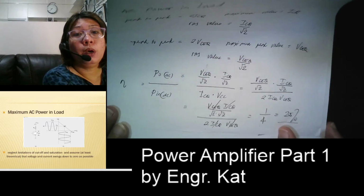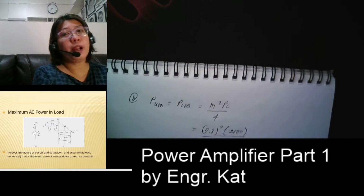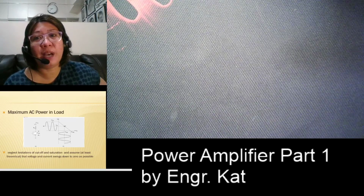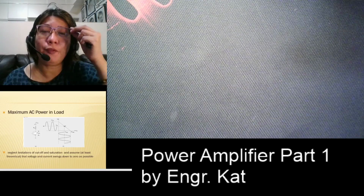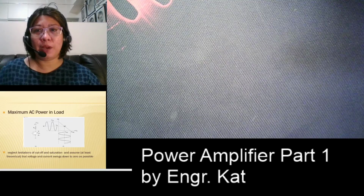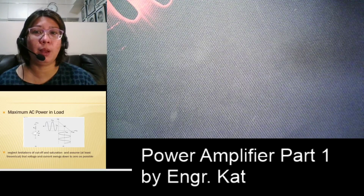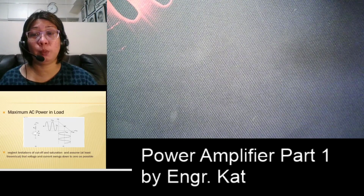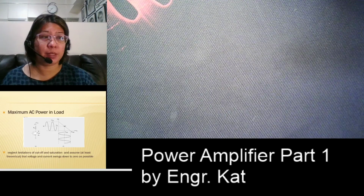Okay, so we are usually expecting a value that is lower than 25%. 25% is usually not common because it is a maximum value, and we use a very, very large signal there, which is not allowed for class A. So when you are solving class A amplifiers, what do you expect? You expect a value which is always lesser than 25%. Okay?